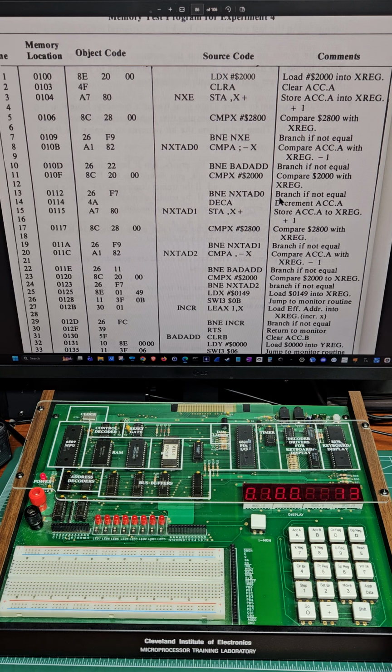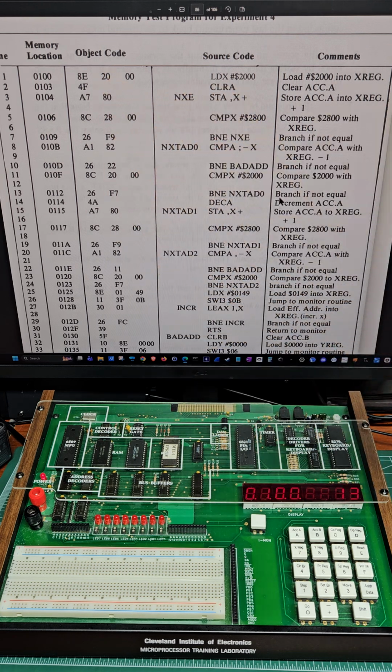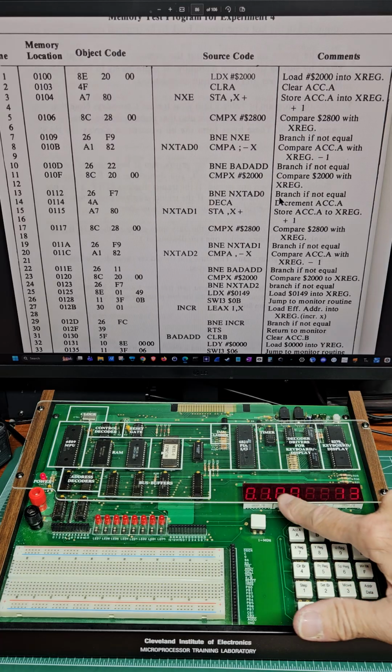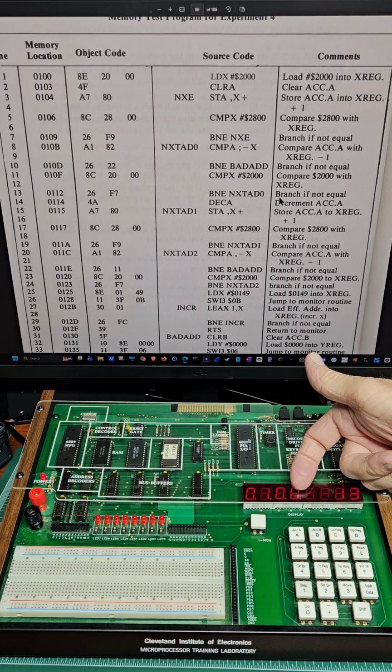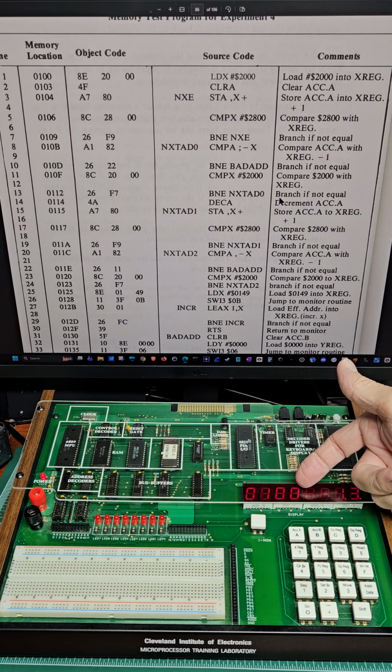It's really not too hard, but it's kind of tedious and can be long. This is a really short, easy program just for comparing RAM. Now, right now it's set to change the address. You can tell because you've got the dots on the address. When you hit the address button here, it changes, putting the dots on the data part. So now when you type something on here, it changes the data instead of changing the address.